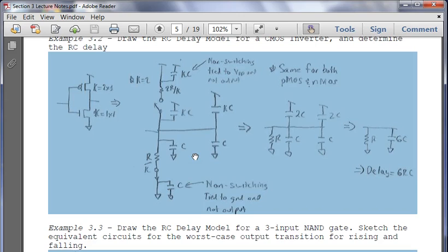So this is kind of a fundamental proof of something that is widely known. Yes? How did you determine the K? K is determined by, for PMOS, it's 2 times the number of circuits that go through the path. For NMOS, it's 1 times the number of circuits that go through the path. So K for PMOS is going to be 2 times 1, because we're only going through 1 PMOS. K times 1, here's 1 times 1, because we're only going through 1 NMOS.